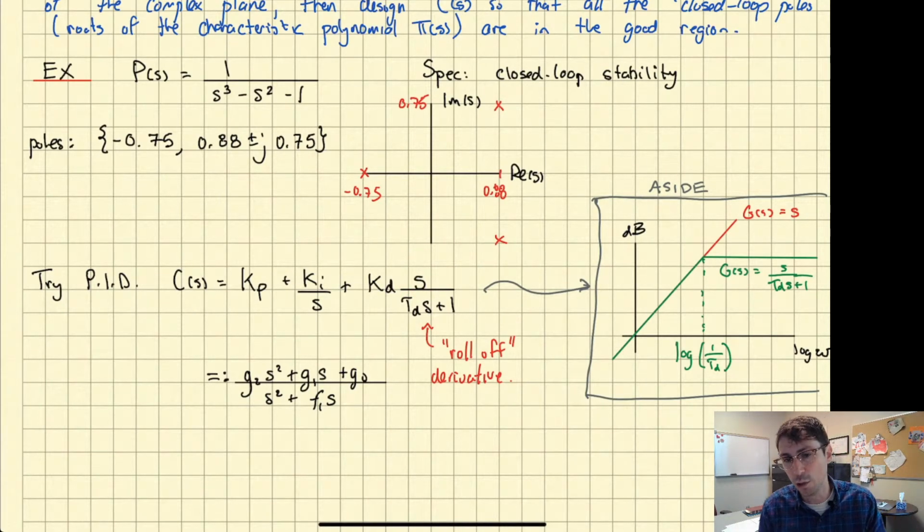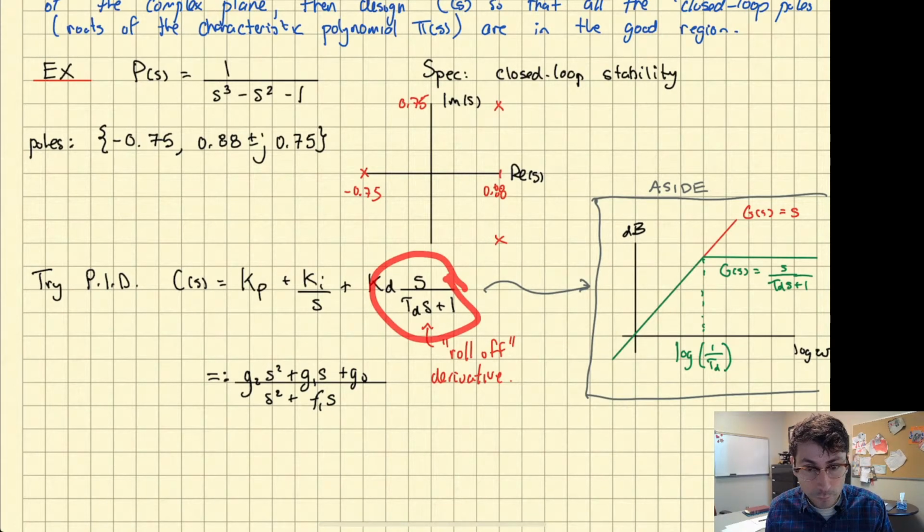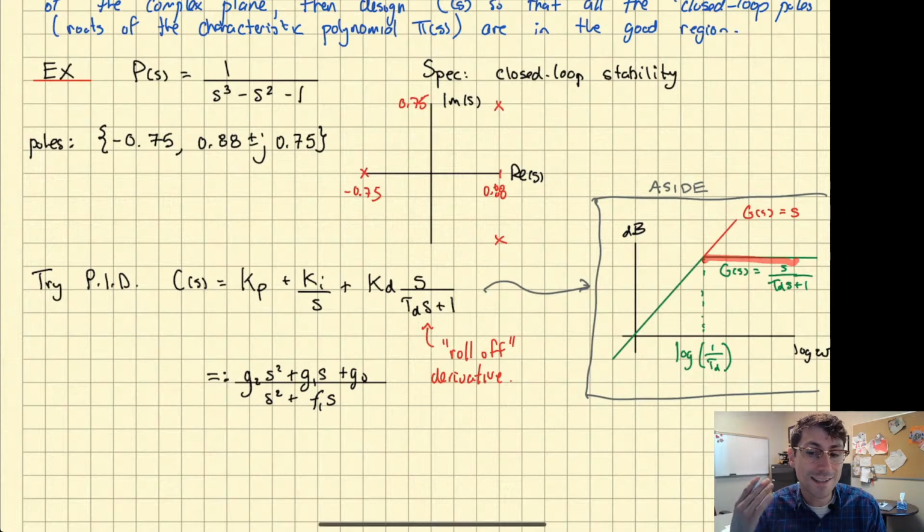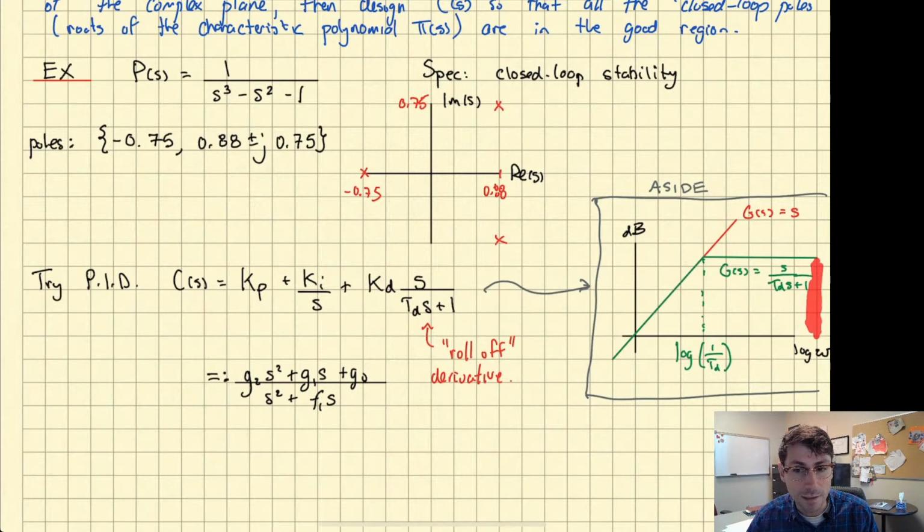So of course, what you do is you approximate it when you implement it. It's common in PID control to accept the fact that I can't implement a differentiator perfectly, and then cut it off at a certain frequency. That has the nice benefit that it caps the amplification of high frequency noise. Notice that my approximation to the differentiator has a maximum gain for high frequency noise, whereas with my ideal differentiator there's no cap. It's going to keep amplifying higher and higher frequency noise.